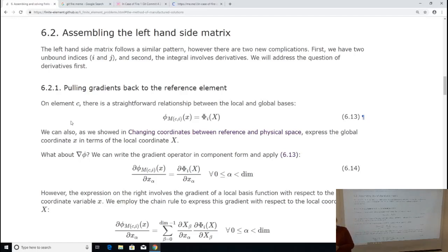So when I write grad u in the PDE, that means the gradient in physical space. That is to say, it's d phi, or the function, but once I expand the function into a finite element space, that's just d phi d little x for all the components of little x.